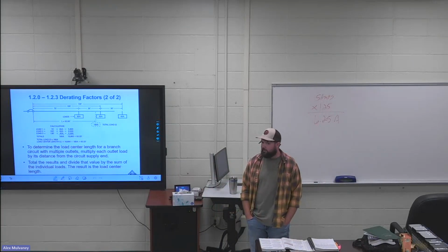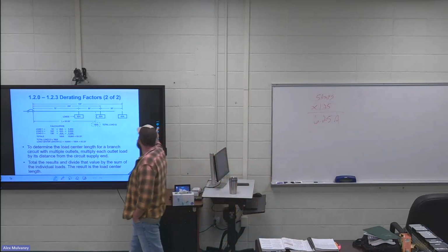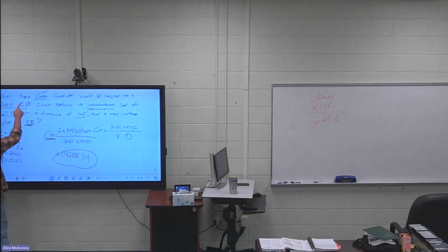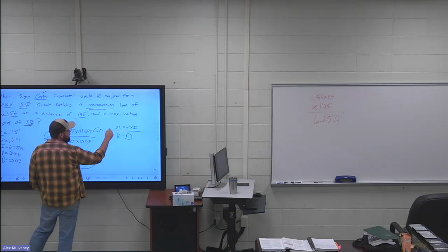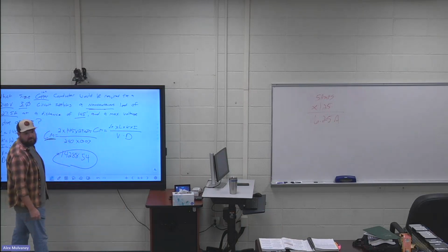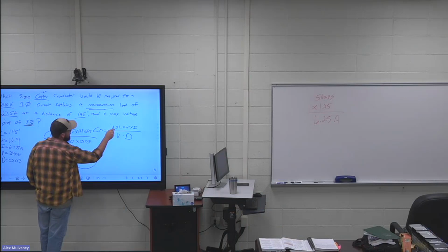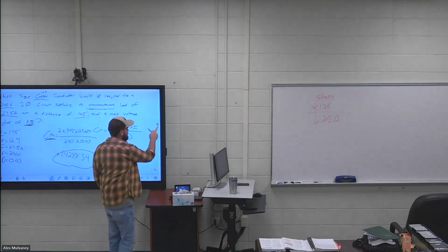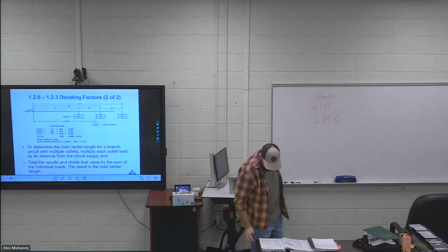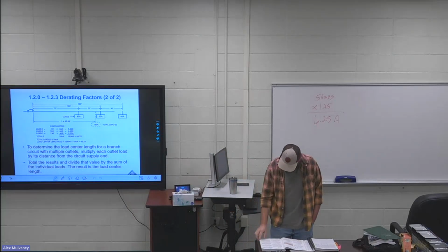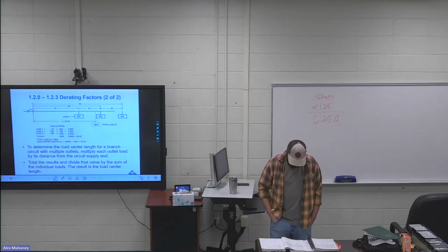So all you're doing there is, if you saw this question right here, and it said 3-phase, you would have to do this voltage drop equation. Instead of having 2, you would have the square root of 3. That's it. You just have to watch what you're looking at. I'm not going to go too much into those because it's the same thing, just one number is different.